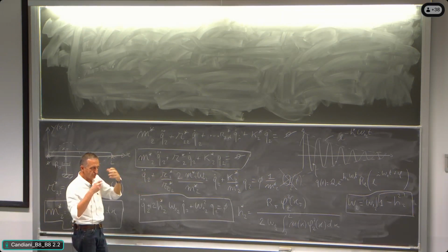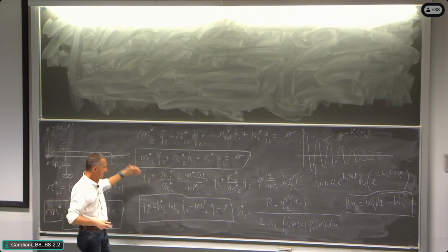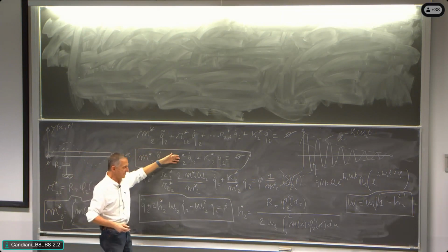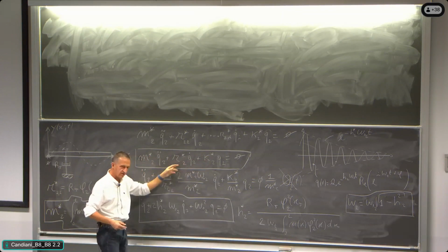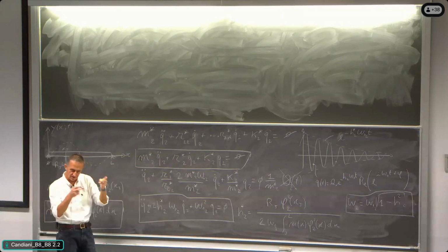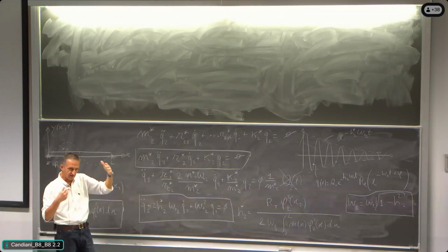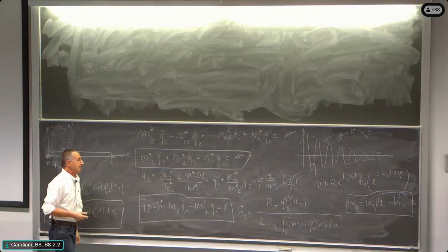If we are not looking at the extra diagonal terms, we have the modal mass for mode 2, the modal damping for mode 2, the modal stiffness for mode 2, but for sure it is a double index in the n degree of freedom problem, it is the index 2, 2, all right?